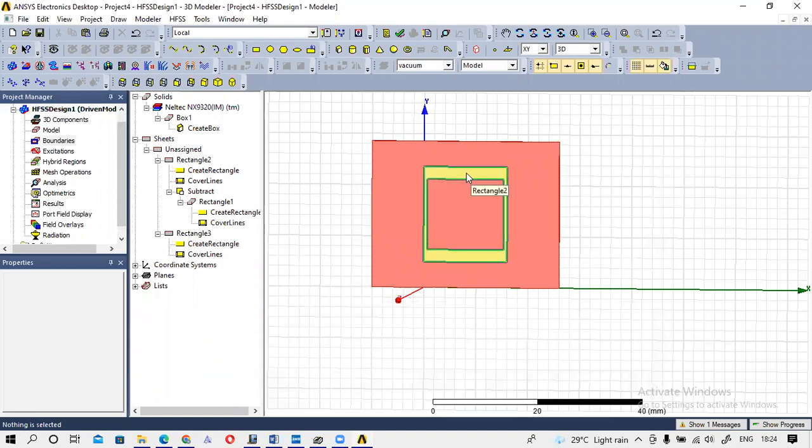So you can see that we have prepared this high impedance section. The low impedance section is 2.4 millimeter width, and these are the high impedance sections, that is 0.64. Okay, so we have almost completed our branch line coupler.